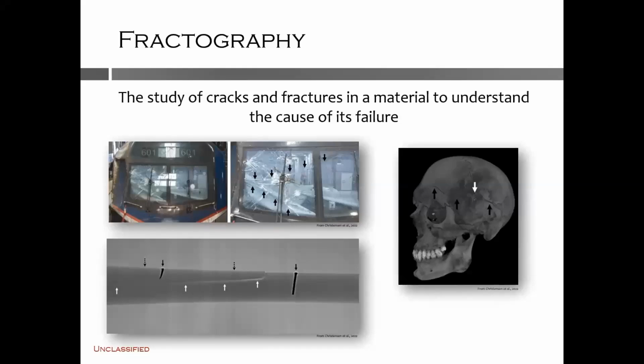Fractography can be used to determine the point of origin of a fracture, identify the presence of flaws and localized stress concentration, identify material limitations, and reveal information about the microstructure and mechanical properties of the material. Fractography is frequently used in the failure analysis of engineered structures and products, often to ensure the reliability and safety of the materials. But it's also used in a variety of forensic investigations, including failure analysis of glass, ceramics, plastics, and metals.